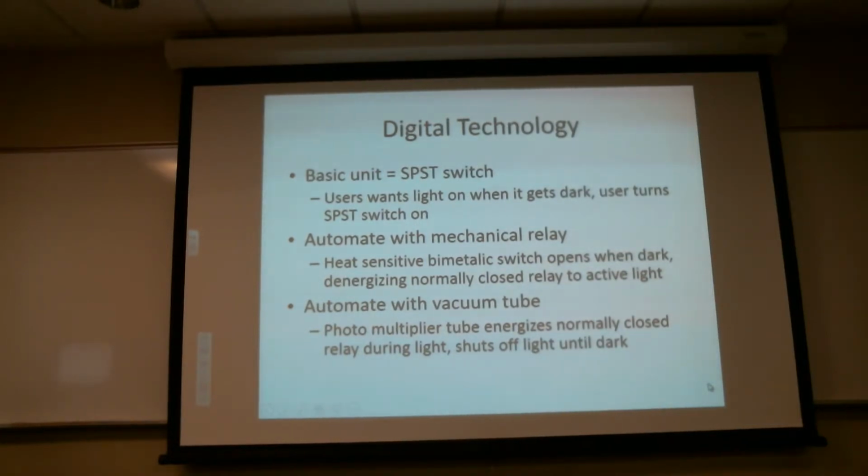And this is particularly true in an environment where I may be getting a variable voltage or not too stable power source voltage. So oftentimes I may want to have a decision-making voltage that's quite a bit lower than my source voltage. That way, if I get some variation in source voltage, my decision-making remains the same.